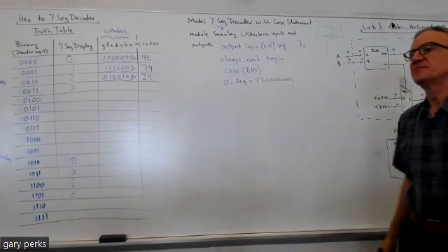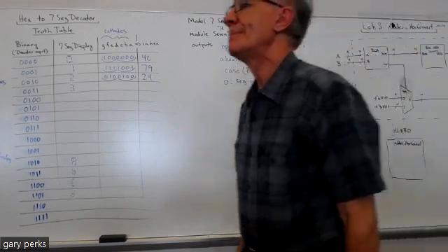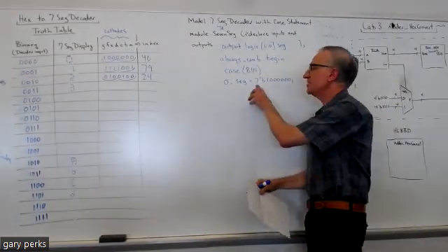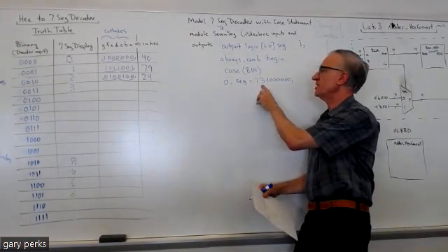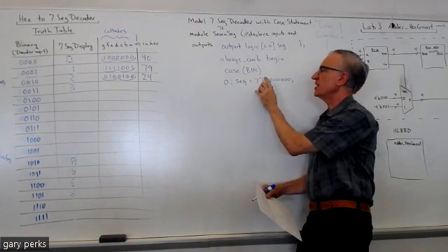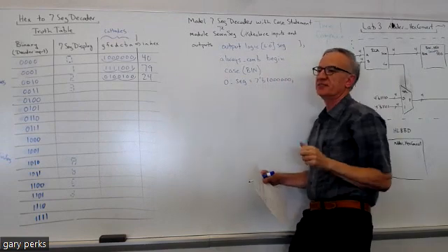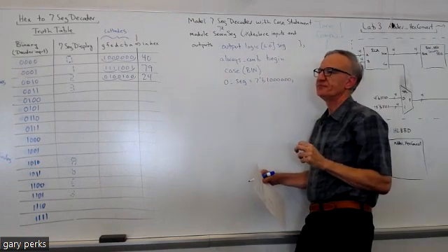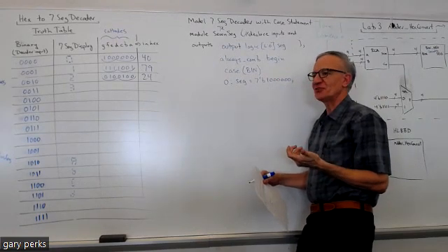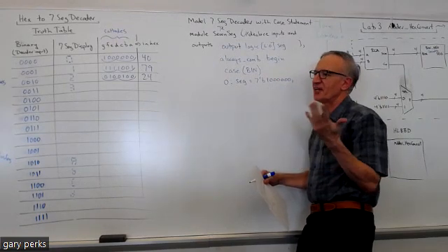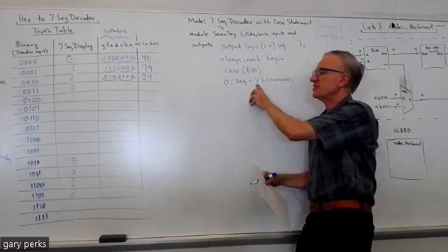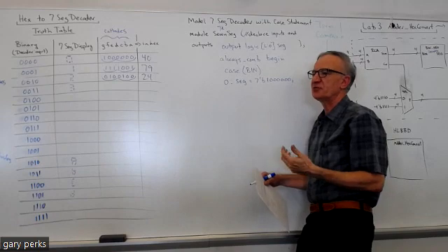Oh, question. Is there a way in System Verilog to display hex values? Yes. Instead of doing 7 tick mark B and then the bits like this, you can do 7 tick mark H and then put 40. You would think it would be 2, right? There's 2 characters, but that's what I thought when I first did it. But it was showing error. You have to put the same number as what bits would be.